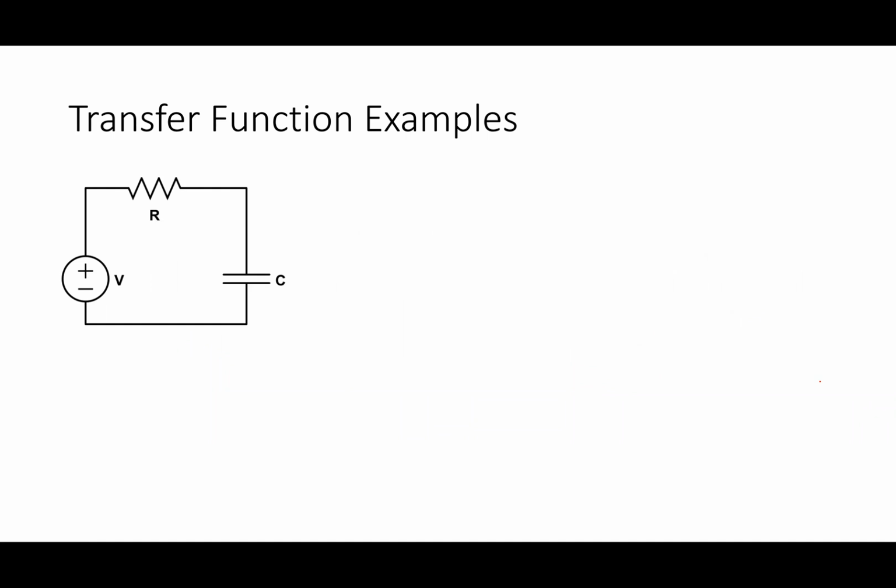So let's say we can figure out all kinds of transfer functions from this thing. Actually, at least I can figure out 2 or 3, right? So we'll get to Eli's question. Let's say I wanted to figure out I of S, okay? And my input was V, right? So actually, in reality, I want to figure out I of T. I want to figure out what the current looks like as a function of time. That says, take the Laplace of the whole circuit. So what do I do over here for the Laplace domain version of that circuit? I don't write C, right? What changes do I make here? 1 over SC.